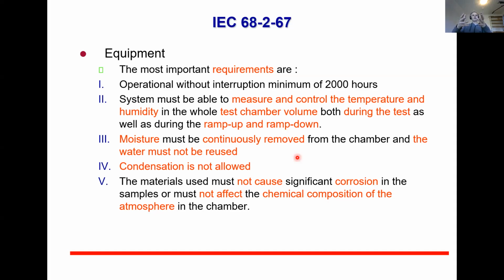Therefore, you need to always have fresh, pure moisture exposure to your test devices. And an important thing, condensation is definitely not allowed. In every location, the relative humidity must stay below 100%.